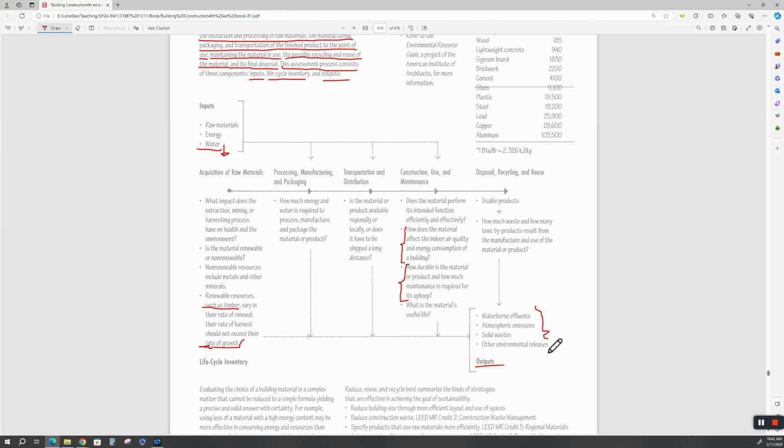Remember me talking about asbestos siding? It was a cement asbestos, and then you had asbestos floor tile. Best thing to do is cover it. Don't remove it, because then you're going to have asbestos remediation, and all kinds of people are going to get involved in this, and you may not even get a permit to dispose of it. So the best thing to do is cover it.